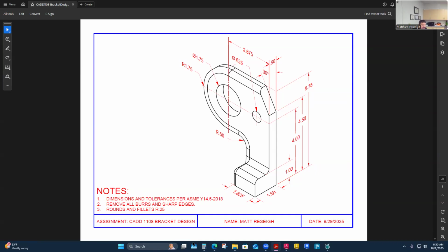Yeah, some projections. I love it. What I'm looking to finish out my top view is maybe what this thickness is right here, because I should see, and there's also some fillets going on here too, which I think are all quarter-inch radius, but I need this 1 inch up here so I can show this foot. My top surface is right here. My eyeballs are actually right here, perpendicular to this surface. I'm seeing this surface, but it's actually down and away from me. So I'm going to put in this surface that's actually right up against my eyes here.